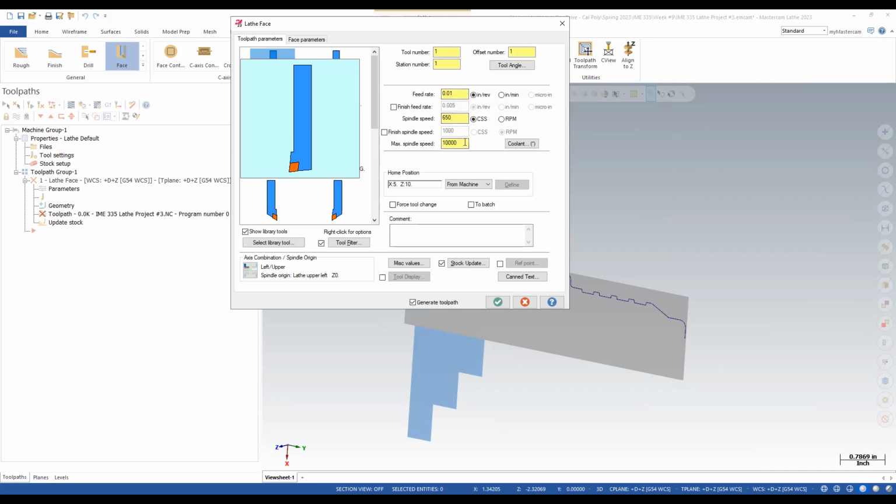So we're good here. What's the max spindle speed on the tool room lathe? 2000. Thank you. So 2000. We're going to still spindle speed clamp it. We're going to spindle speed clamp it at the max. Sound good? We're going to still put the number in so it's legit.